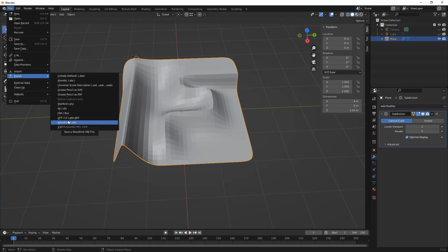We've already taken a look at the fact that FBX is the main one that brings appearances with it. But now OBJ and STL are also supposed to carry those appearances. So the main thing that I want to do is I want to pick a format that works. STL and OBJ are probably going to be the most relevant, at least for right now, because they allow us to insert it as a mesh.